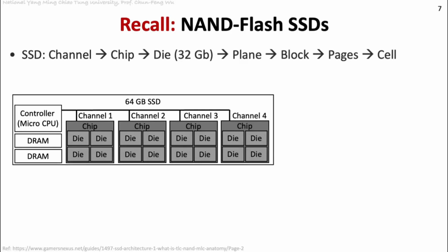For example, if you send read-write requests into the chip, you can send up to 4 requests and they can run concurrently. But if you send more requests to one chip with 4 dies, then only 4 can run in parallel, and the others will be pending, until one die finishes its request and can then serve the 5th or the 6th one.